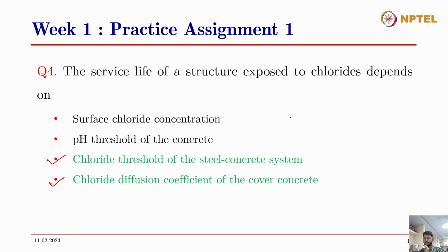But assuming that there is sufficient cover, and the chloride threshold is sufficiently high for the service life of the structure to be well consumed, and for the structure to remain serviceable throughout its design life, then I don't think the surface chloride concentration will make a difference to the corrosion process.